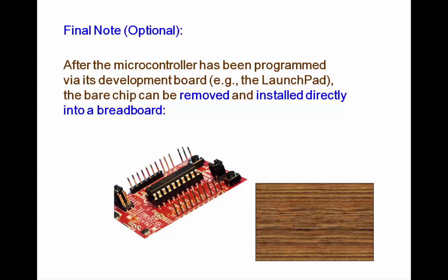One final note, and this is optional for all of the experiments, but a good thing to know if you decide to experiment further with your microcontroller. The purpose of the Launchpad board, the red board, or the blue board in the case of the Arduino, is to give you an environment in which you can interface the microcontroller to the computer via the USB cable, and also provide some diagnostics as to what's going on inside the chip.